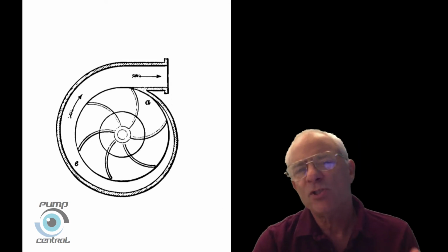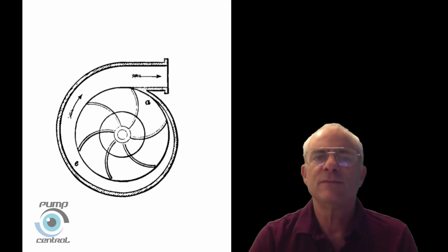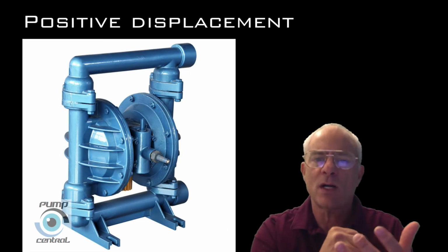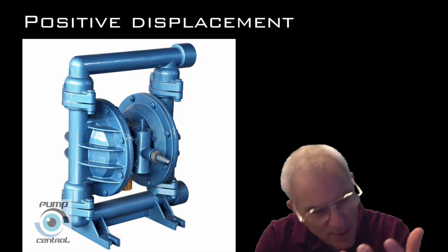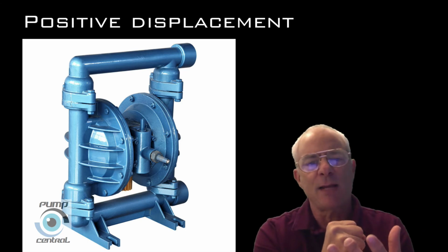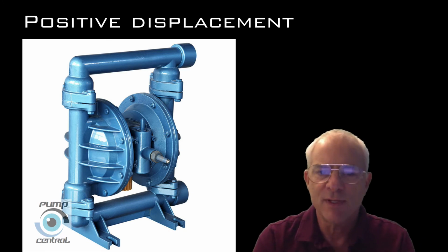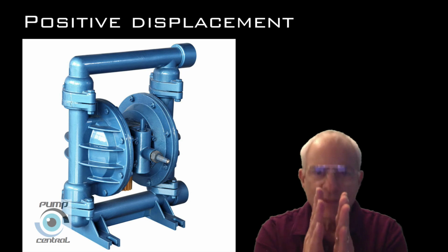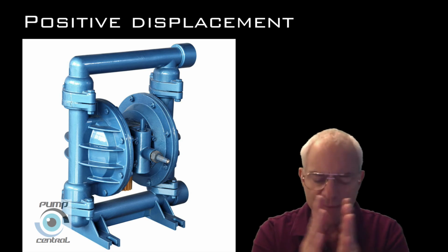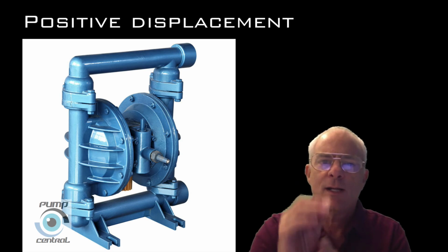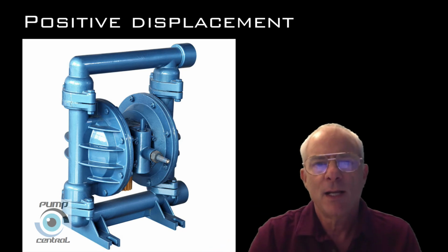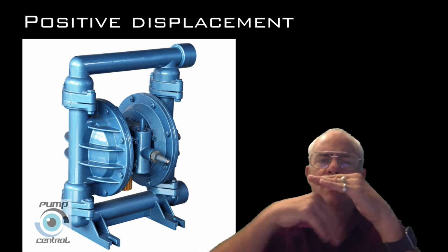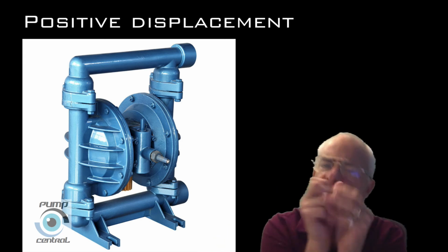Many pumps push water, and they're called positive displacement pumps. They positively displace the water from where it is, and they keep doing that. A plunger type pump does that sort of thing. A diaphragm pump will do that sort of thing. It's pushing the water as opposed to throwing. Soft impellers that collapse and close the area inside the volute, pushing the water out.